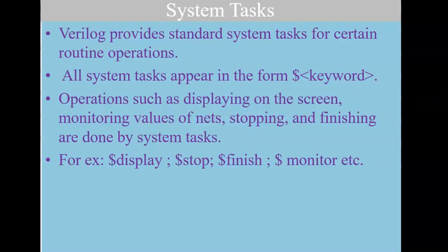Now, Verilog provides some system tasks. Inherently, it has some built-in system tasks. Task means some work, as I have told you, a procedure. So what are these system tasks? Normally, these system tasks appear with a dollar sign followed by the task name. The examples supported by Verilog are $display, $stop, $finish, $monitor.